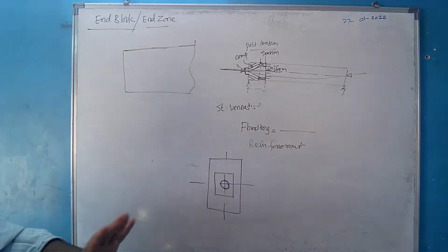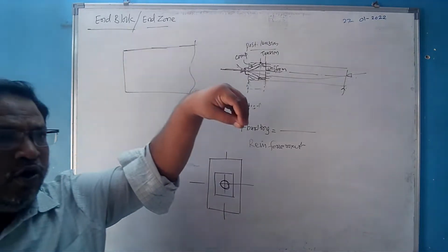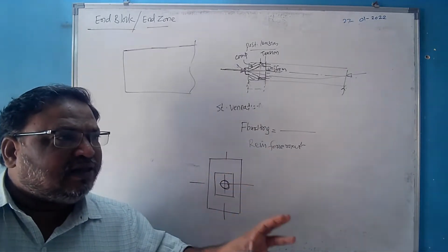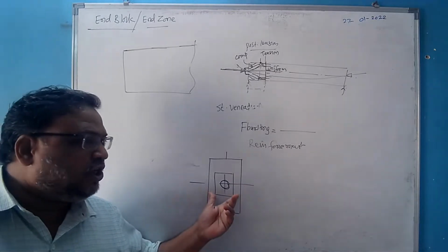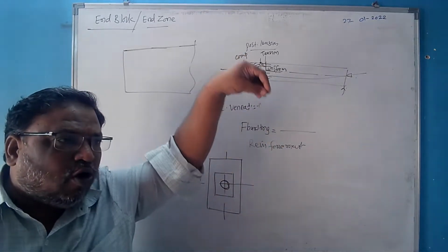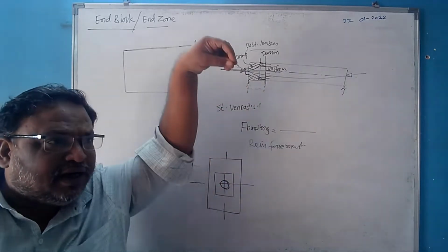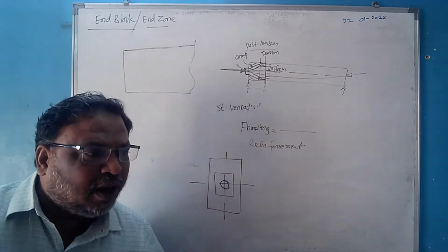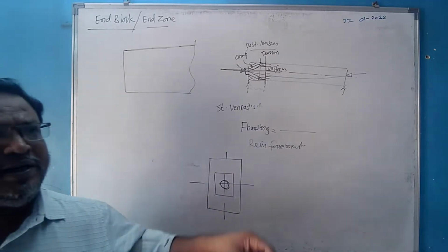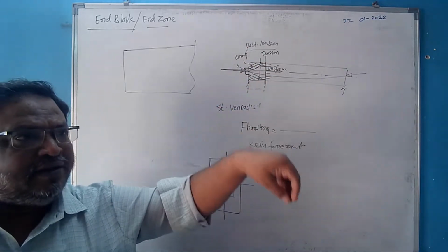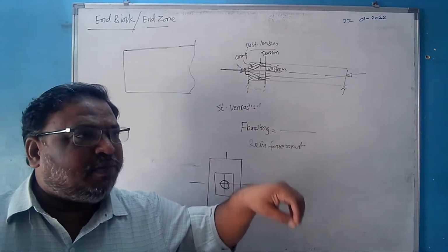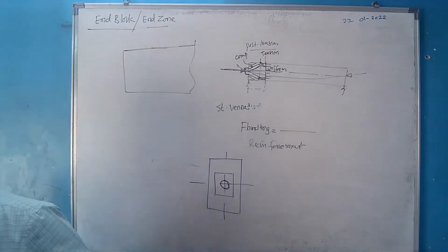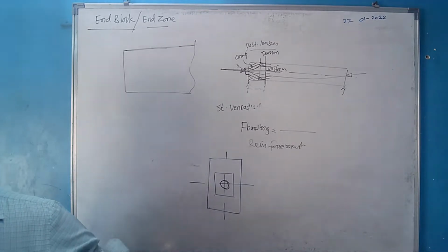अगर हमने greater area पर distribute नहीं किया, so a concentrated load will be acting at a point, and because of that the stress concentration will be there, and there is possibility that the concrete may get crushed here. And in case of the columns, अगर कॉलम को मैंने डायरेक्टली सॉइल पर रख दिया, so the greater magnitude of load will be acting on a very small area, और वहां पर सॉइल का बेयरिंग कैपेसिटी बहुत कम रहता है. Because of that there is possibility that the column will penetrate in the soil. सॉइल का एक्सेसिव सेटलमेंट होगा and the structure will be observed with cracks. You will observe cracks in the structure because of the settlement of the soil.